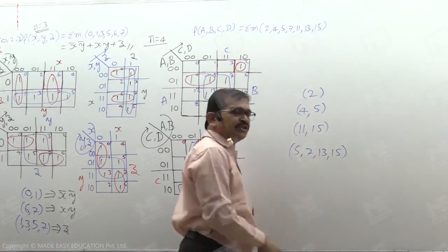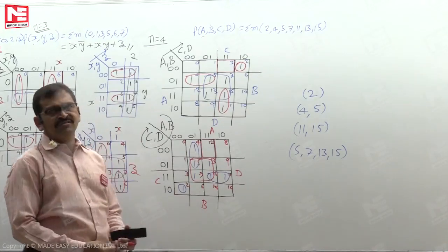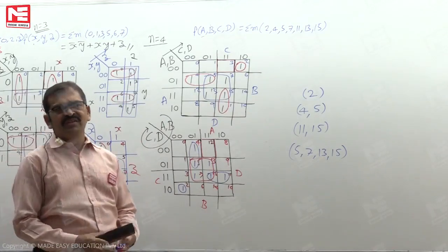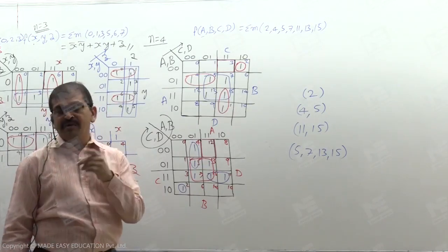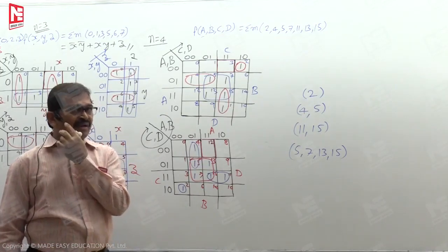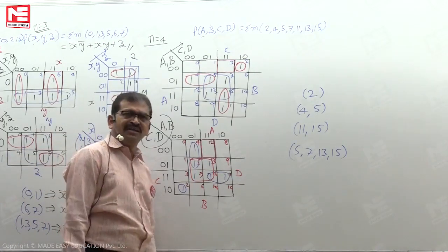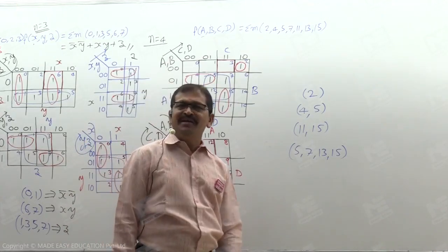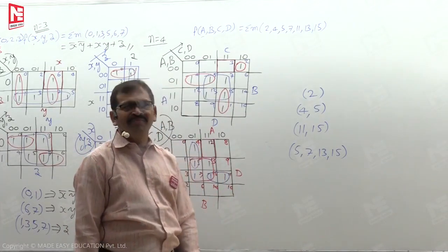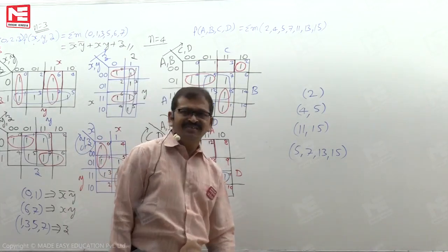So with this 4-cell subcube, we are having coverage of all the cells. Coverage of all the cells means we are referring only to the cells which have a functional output of 1. We already mentioned that. Hence, as far as the marking of the subcubes is concerned, it is a terminal step. The later work is reading the product form. You try yourself.